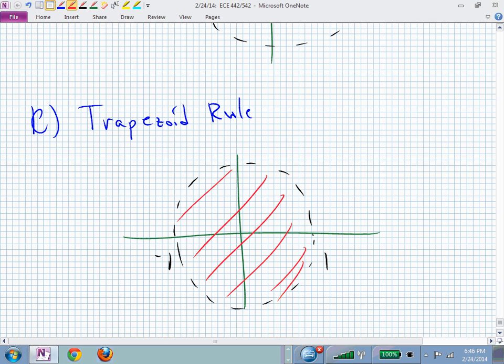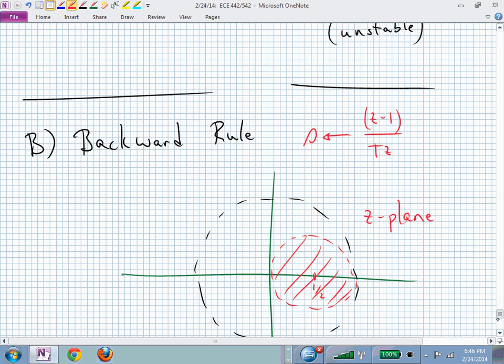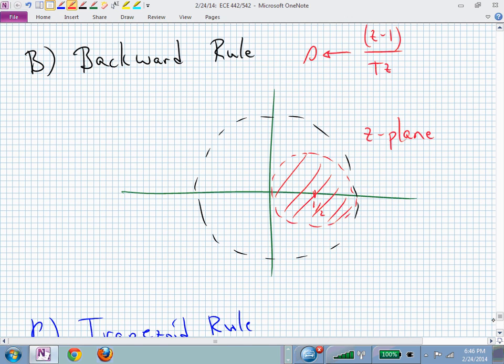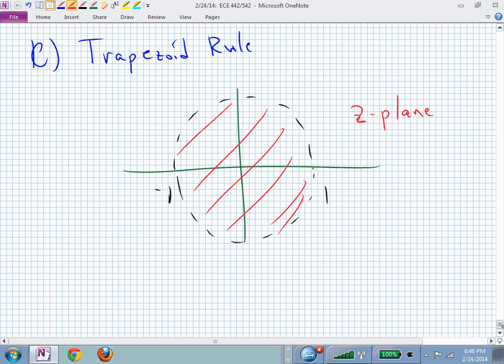Here is our z-plane, meaning it doesn't restrict to a much tighter region. It actually maps from one stable to the complete stable region in the z-plane. And I'm not sure I'm going to show that, but you can just see that you now have two ways of producing stable transformations going from h of s to h of z with numerical integration.